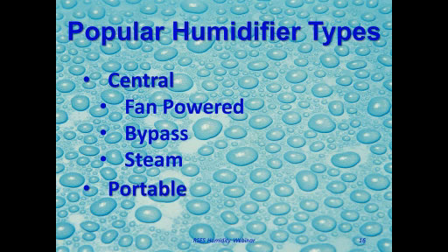So the best situation for a central humidifier is when water is no longer needed to provide humidity to the conditioned space, that you actually have all of the water that's inside the humidifier drain away. So there's no standing water during off cycles. And that drastically reduces maintenance.